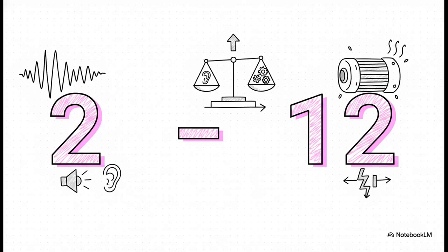Now, what's really fascinating here is this specific number range, 2 to 12. This represents the PWM carrier frequency in kilohertz, which you'll find at parameter 02.03. This is a brilliant little setting. By adjusting this carrier frequency between 2 and 12 kilohertz, you can actually fine-tune the acoustic noise of the motor against the electrical performance of the drive. A higher frequency means a much quieter motor, but it can increase heat and leakage current in the drive itself. It's just a fantastic balancing act for the informed engineer.